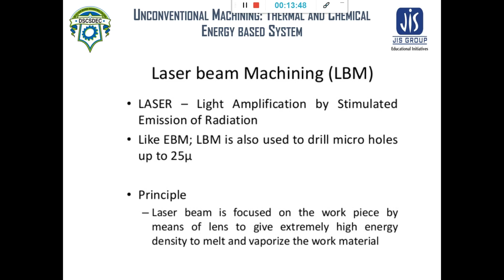Now laser beam machining. Laser means light amplification by stimulated emission of radiation. A high energy, high power density laser beam is focused onto the workpiece to melt and evaporate the material from there. The laser beam is focused on the workpiece by means of a lens to give extremely high energy density to melt and vaporize the work material.